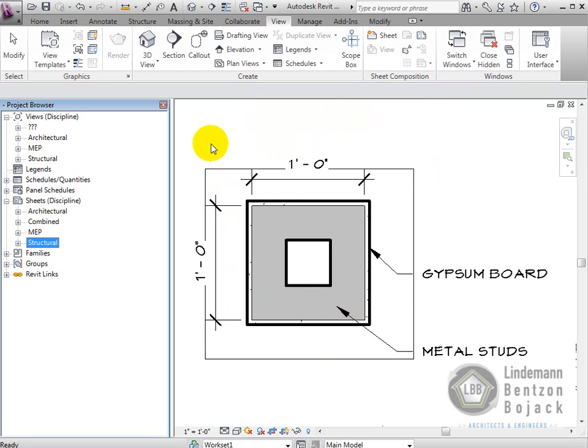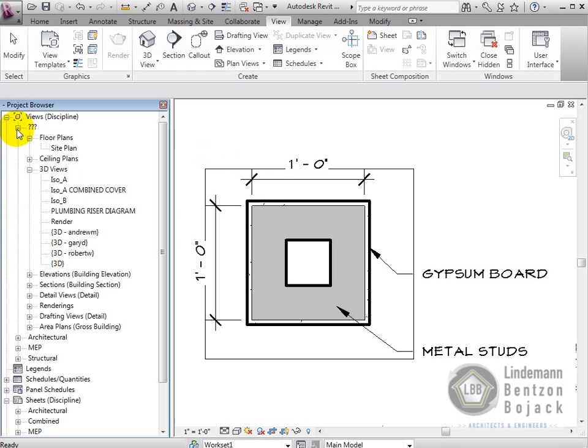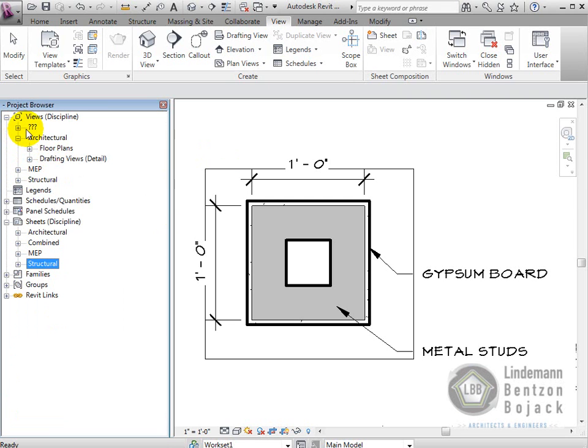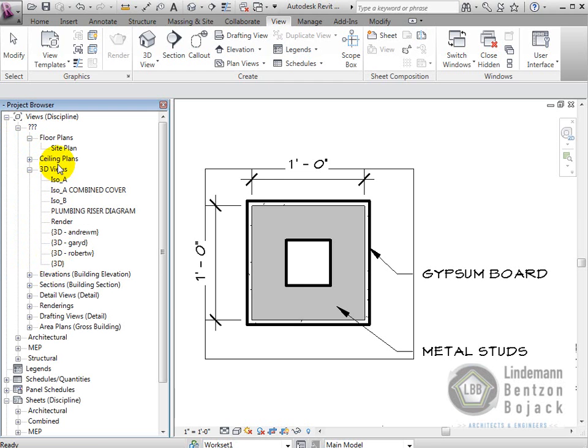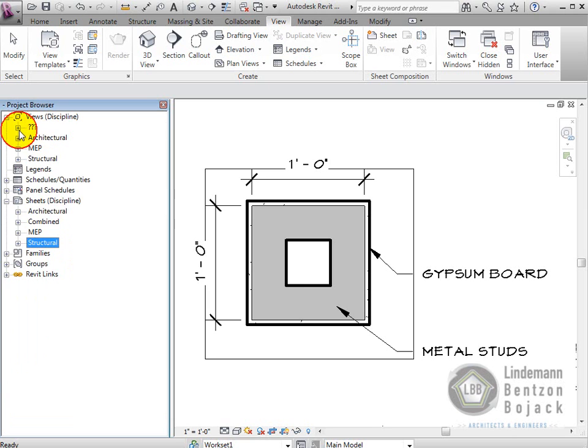So you have many pieces here to remember. You have the shared parameter file, then you import that parameter and associate it to a piece of the project browser, whether it's a view or a sheet. Then you go into your browser organization and assign it. But keep in mind, you have to go through and assign parameters to all your views. Notice under views I have a question mark. That's telling me that all the views under this question mark tab have not been associated with one of those parameters so that they would get organized. So it's very easy to know what you didn't do yet. Until the question marks are gone, your entire project will not be organized.